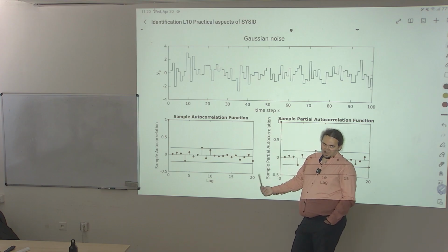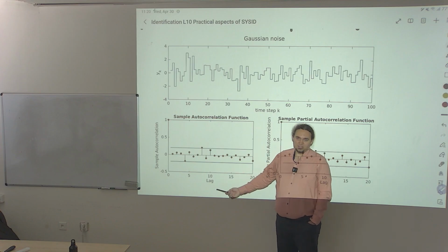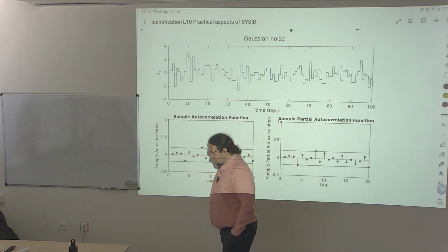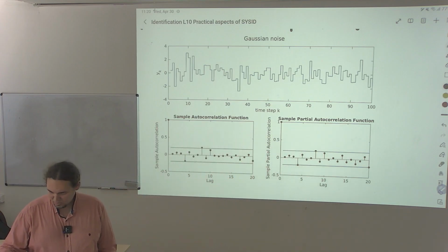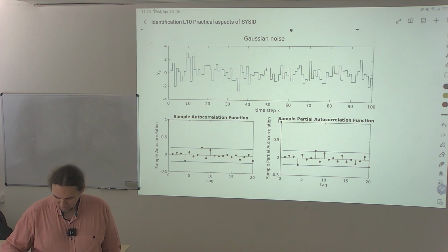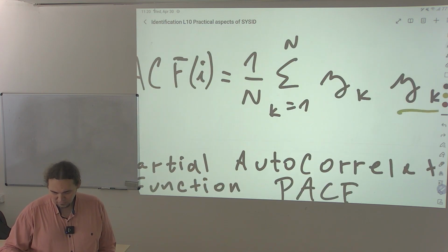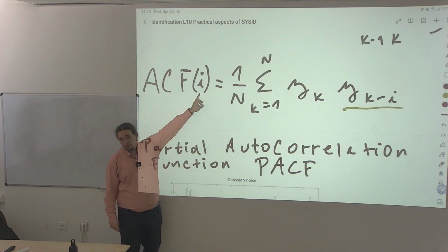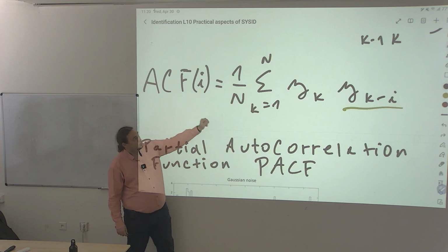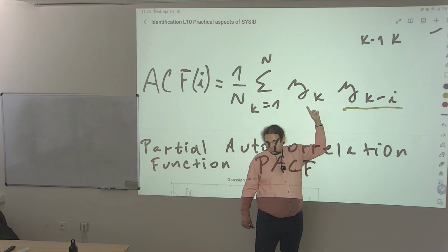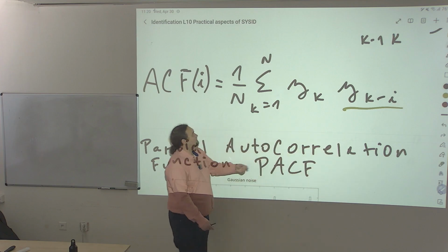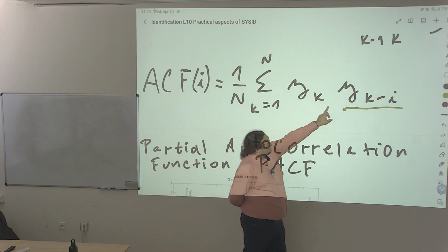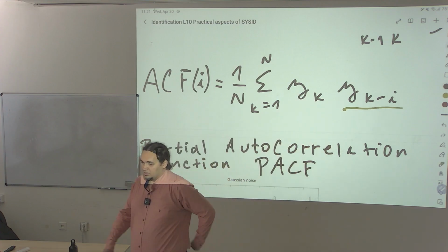Here on the horizontal axis, we have something traditionally called lag, which we would maybe intuitively call delay, but this is really the values of the index. What is plotted there is this function. For 0, it will be basically a correlation of the signal with itself. For the ACF value at 1, it will be a correlation with this signal shifted.